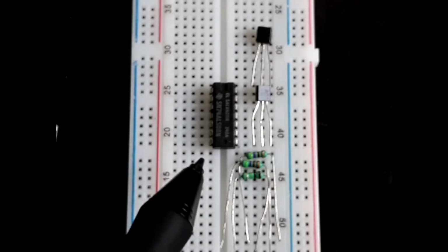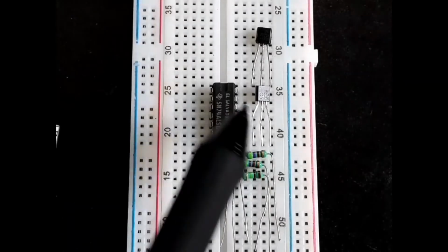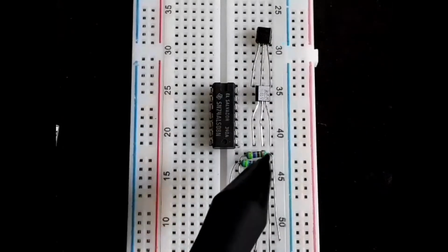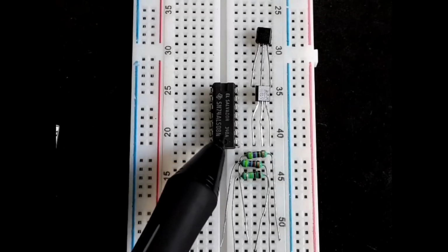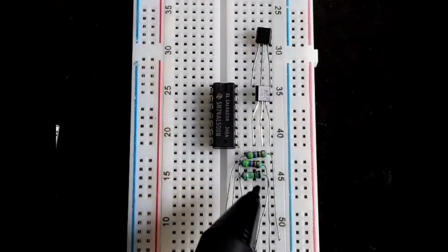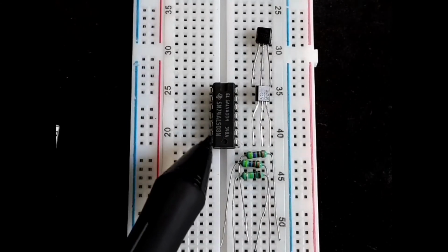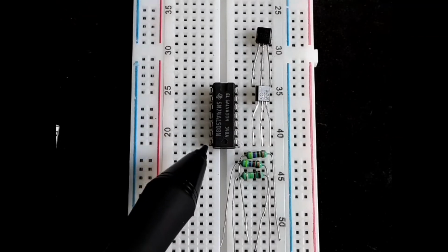You can see here, this is how an integrated circuit looks. So if we use the transistor method of implementing the AND logic, then we need two transistors and few resistors, right? But let's say you want to use two or more AND gates. So then the number of components you need would again increase. So that's the reason we have an integrated circuit here. And the reason it's called an integrated circuit is we have 4 AND gates built into this single chip. And all the components which are required to implement the AND gate is already built into this chip. So that's the reason it's called an integrated chip. And this particular chip has 4 AND gates in it. So let's learn the internal block diagram of this particular IC and understand how to make different connections.